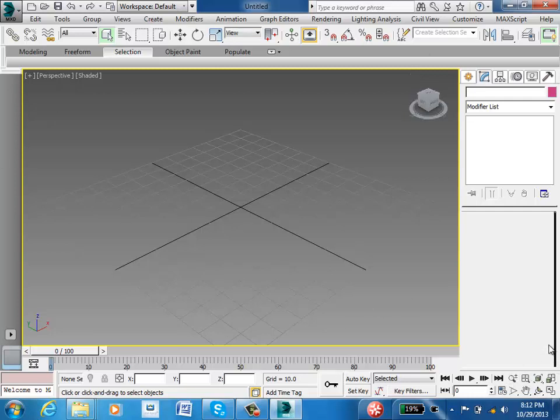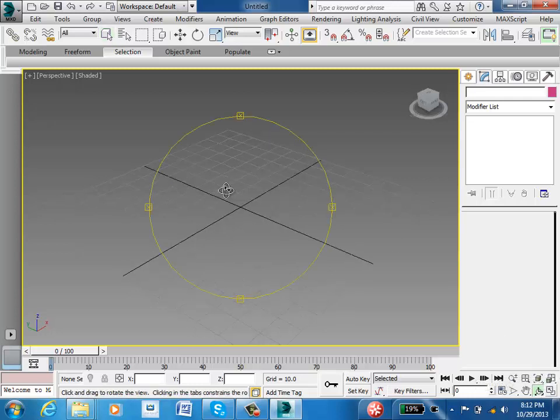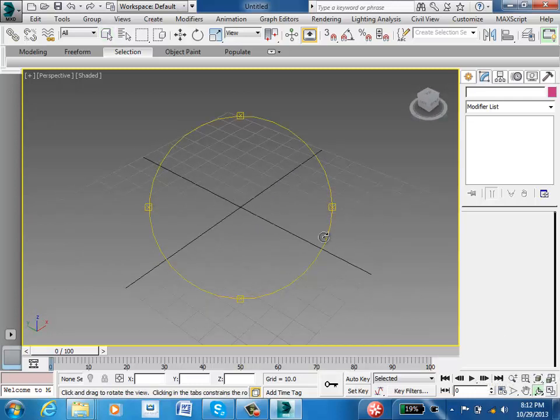The bottom right are navigation icons. We use these to actually navigate around the model. So you can rotate. If you left click and hold, there's a whole series: you can rotate about an object, rotate about the whole model, or rotate about a world point. I always tend to leave this at rotate about the object. Lets me have a little control, so if I select an object, that will become the center of my rotation. You have pan, we can change the field of view, we can zoom in and out, and then we can zoom all or zoom extents.